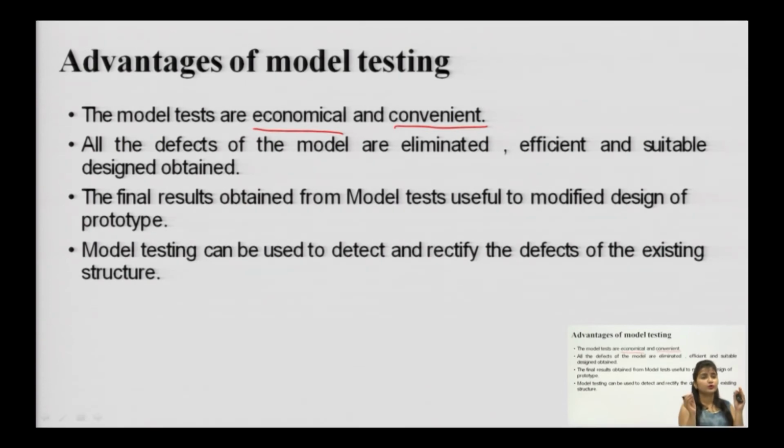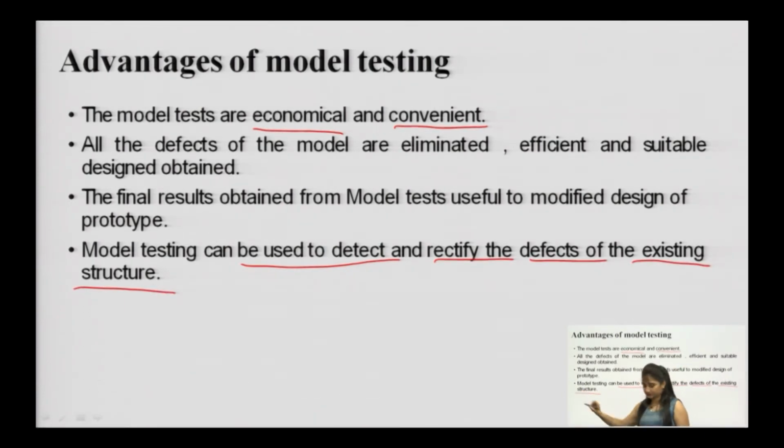So, you can take the dimensions and prepare a model of it, then put the corresponding subsequent loading on it, and hence you can determine whether it can be widened, or the traffic can be taken into another lane, or extra support can be provided from the bottom. This is what is meant by detecting or rectifying the defects of existing structures.